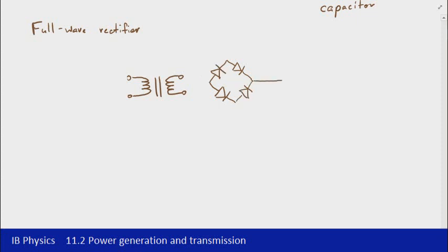The connections then are as follows. We would have our output resistor connected there. That's also going to be connected to the opposite side of the diode bridge, and then from our input we're going to go to the top of the diode bridge and then to the bottom. Now remember that this is not actually a connection here. If those two wires were connected, we'd do a dot there, so those wires aren't actually connected.